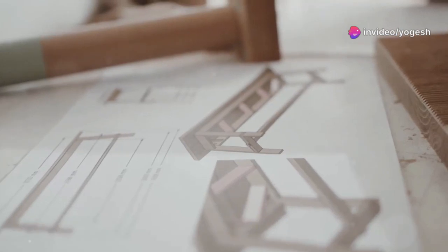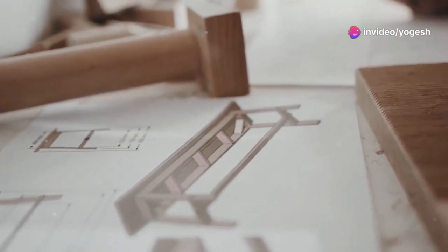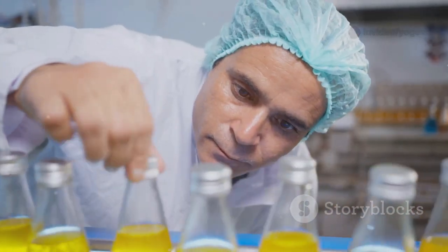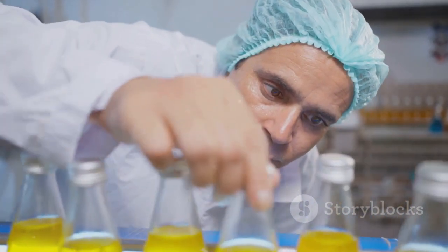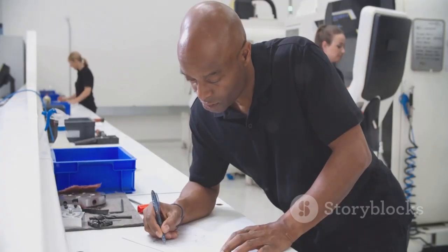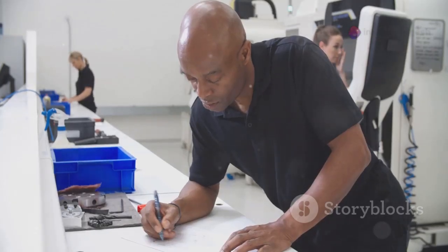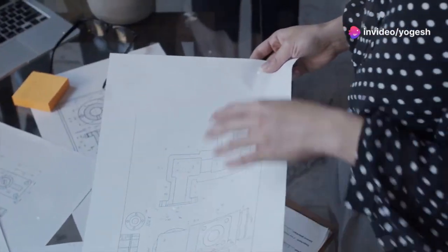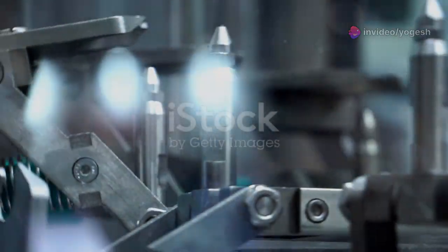Stage tables can include details like torque values, adhesive types, or inspection steps. They formalize the process, supporting quality control and troubleshooting. If issues arise, the table provides a record of the exact procedure. Stage tables turn a drawing into a comprehensive manufacturing document.